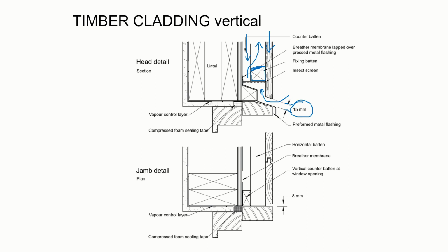Down at the bottom of the opening, we've got some other pieces of timber here which are forming a step and getting it out, making a flashing. So there's a piece of metal effectively that sits down here, and that means that any water down here is actually going to hit that and drain out and drip clear.